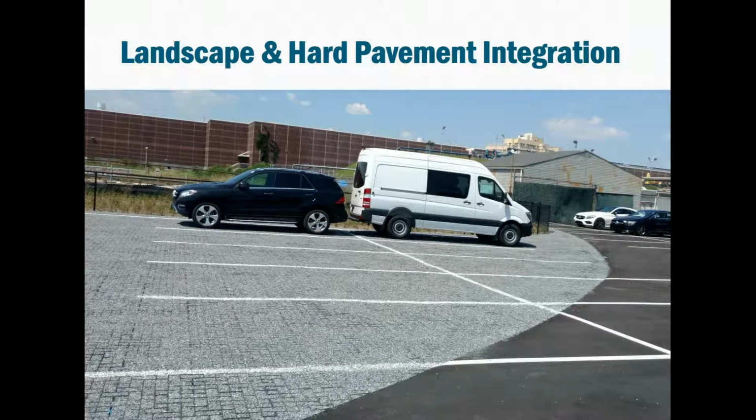Here we see a car dealership parking lot addition. The paver units come in rectangles, but they can be field cut to handle curves, existing structures such as manholes, and other obstacles that are common on site. The GeoPave and GeoBlock units work in concert with hard surface pavements, and they're porous so they can handle the sheet runoff from those adjacent impervious parking areas. This is a great way to add additional parking spaces while still meeting stormwater requirements at a site, with no need to create stormwater infrastructure such as drainage swales or ponds.